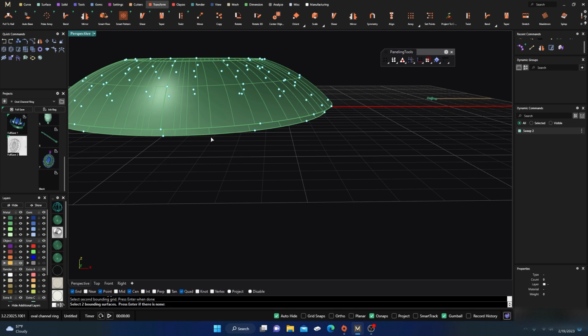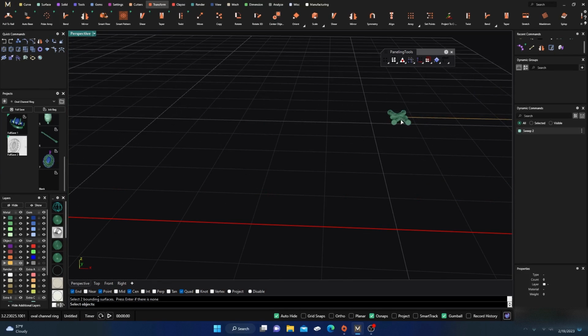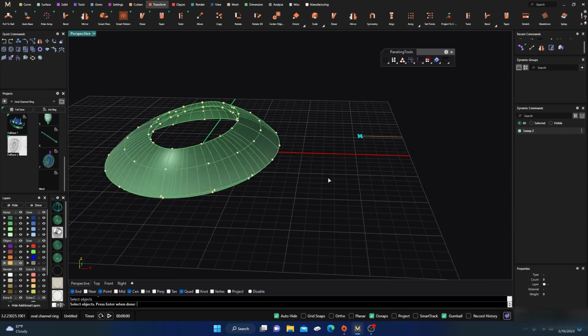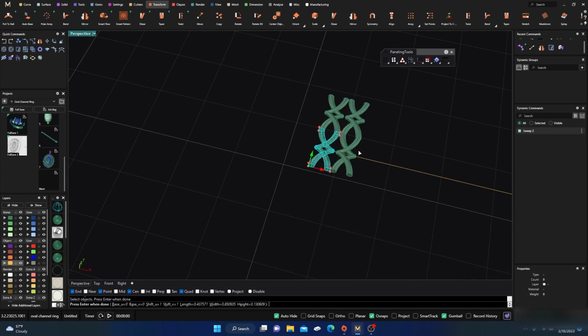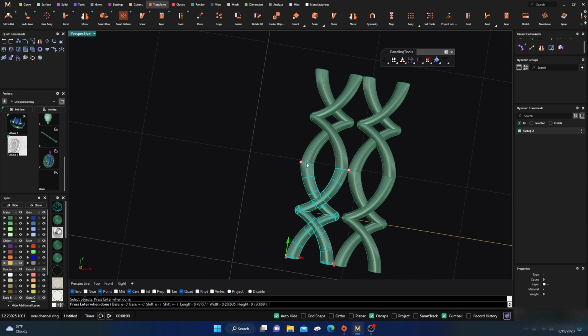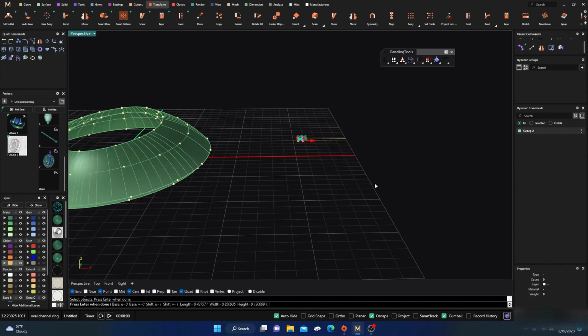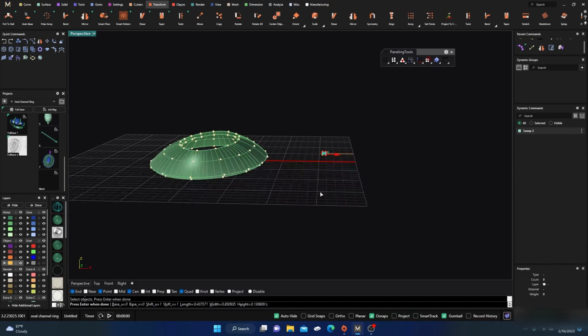And then select two surfaces. We'll select that inner one and then the outer one, and then it asks us to select our object to flow, and that'll be this thing here. And then we'll hit enter. And this is kind of the pattern it'll provide for us, right? And see, since we cut those off, they're nicely butted up. So that's why we cut them off, and then we made them flat. And then we'll just hit enter and give it a little time to flow up on there.